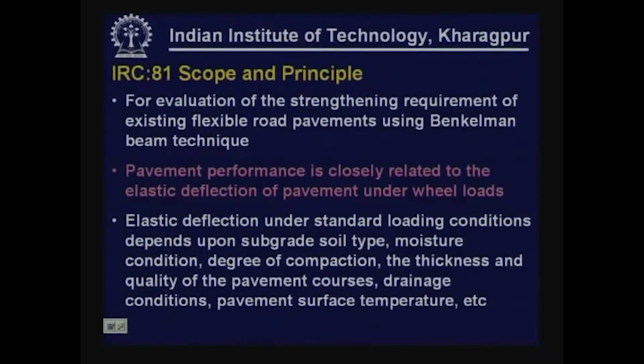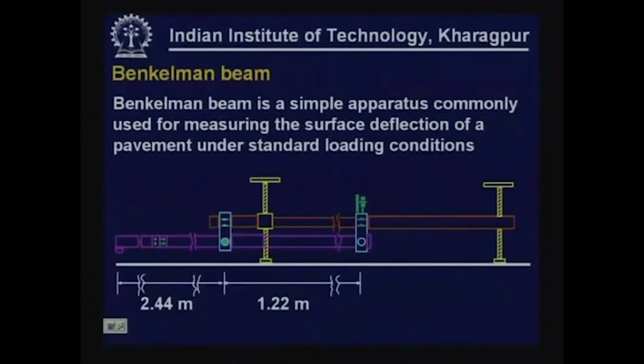So, all the pavement related parameters affect the elastic deformation of a pavement when it is subjected to wheel loads. The Benkelman beam is a very simple apparatus and it is commonly used for measuring the surface deflection of a pavement under standard loading conditions.